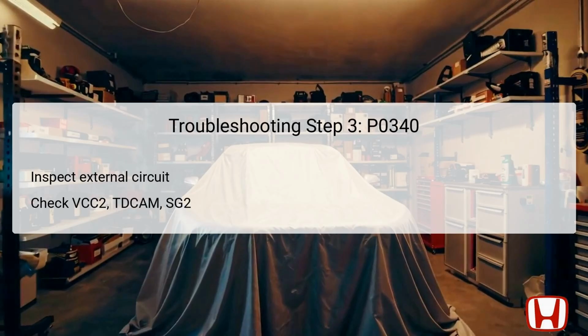Having assessed the CMP sensor A, the next step in troubleshooting P0340 involves inspecting the external circuit, particularly focusing on the VCC2, TDCAM, and SG2 connections. These circuits are integral as they supply power and ground to the sensor and the data pathway to the PCM.